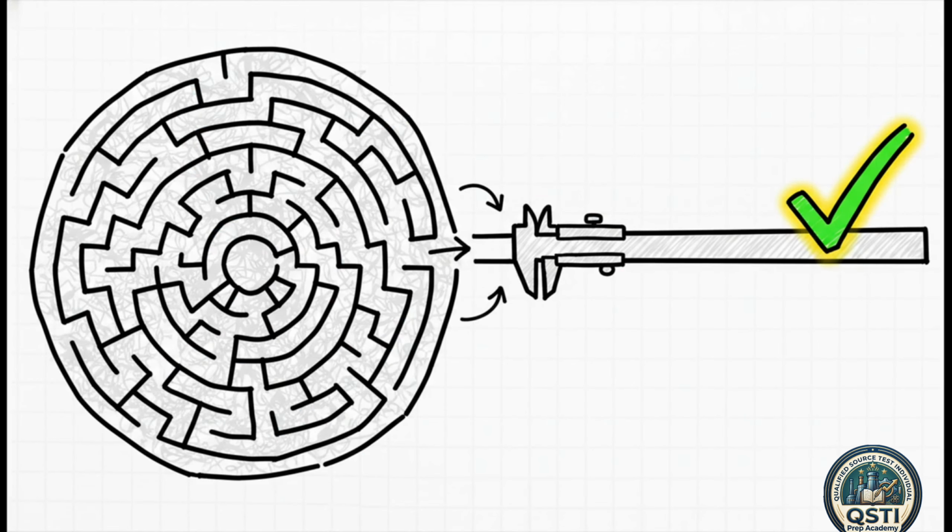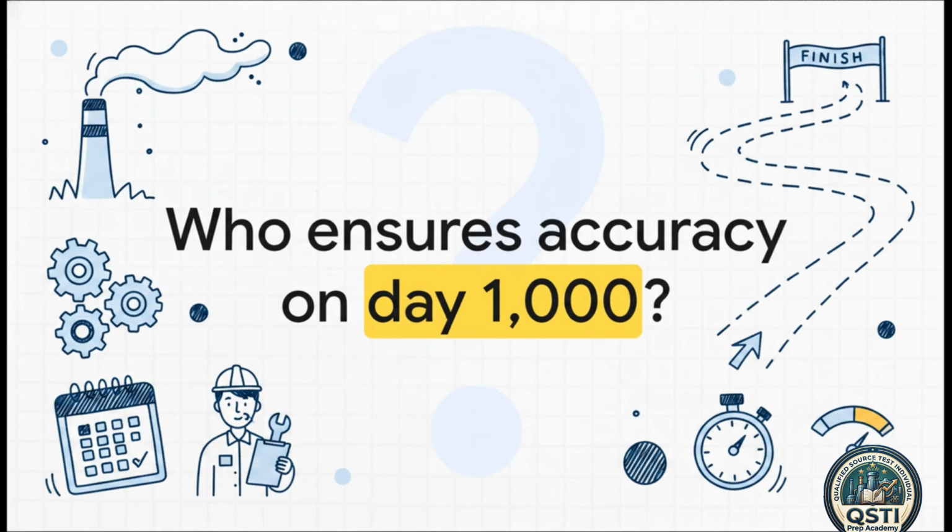Now, what's really interesting here is the alternative pass condition. Remember that simpler equation 3-2, the strict difference between the two averages? Well, the EPA says your results are completely acceptable if the output of equation 3-2 is less than or equal to 1% O2 or CO2. So if your monitor's average is within a flat 1% of the reference method's average, you get to bypass that whole complex relative accuracy threshold and pass the specification outright. A real game changer if you qualify. Once you hit those numbers, your CEMS installation is officially certified under Performance Specification 3.